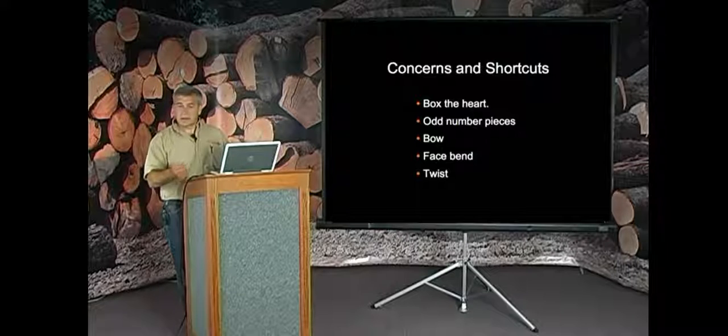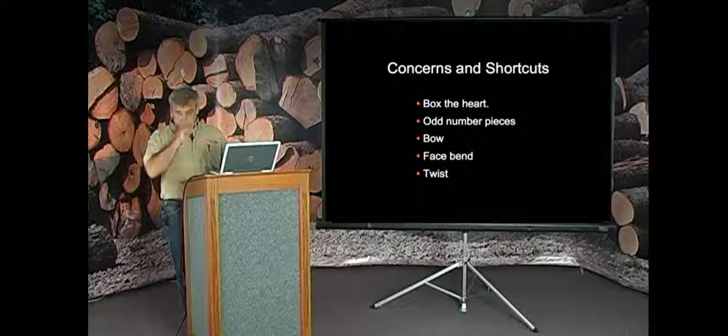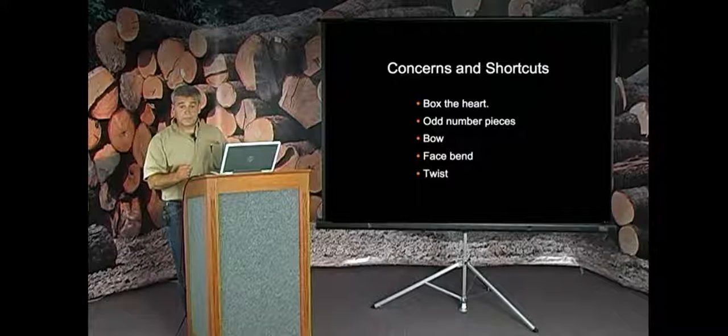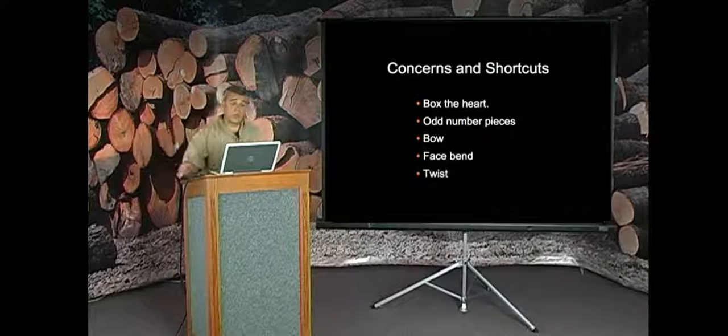I don't know a sawing technique. But the only thing you can do is go short. Short lumber, at least you can joint one face and then put it through a planer and get a consistent thickness and maybe get the twist out of it. But these are all considerations when you are cutting dimensional lumber.